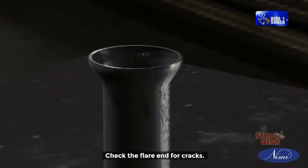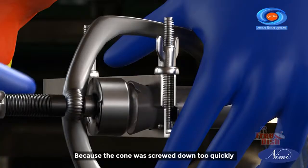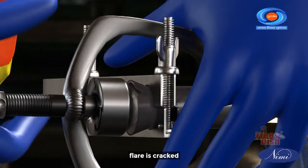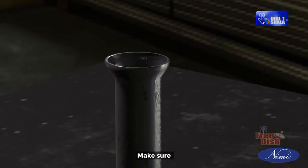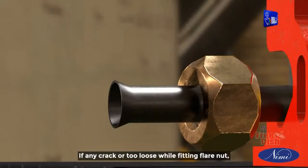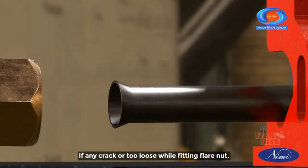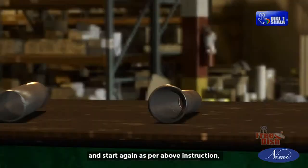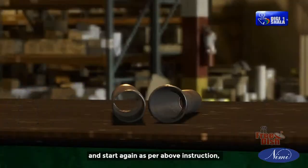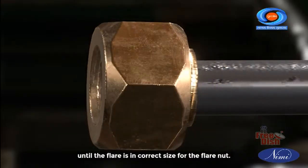Check the flare end for cracks. Note: because the cone was screwed down too quickly, the flare is cracked. Make sure that the flare is the correct size. If there is any crack, or it is too loose while fitting the flare nut, cut off the flare and start again as per the above instructions until the flare is the correct size for the flare nut.